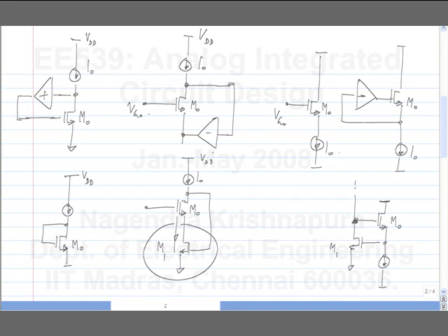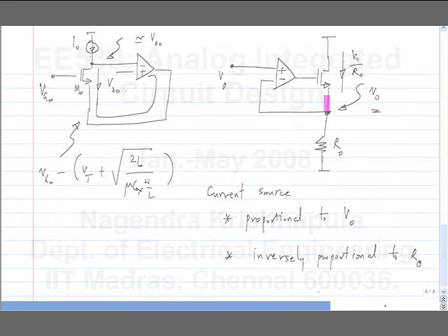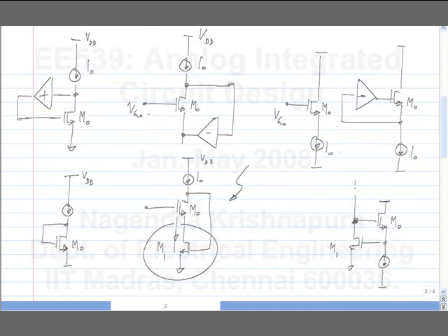See, if you have inductances and capacitances of arbitrary values, and if you assume that your signal is only at AC, not at DC, you can change any of these circuits so that at DC it looks like this, and at AC it looks like any amplifier you want. Okay. So, for instance, but that's not how we use it. In fact, this circuit, what you say is right. This is not very nice. This is not suitable for using M0 as a common source amplifier.